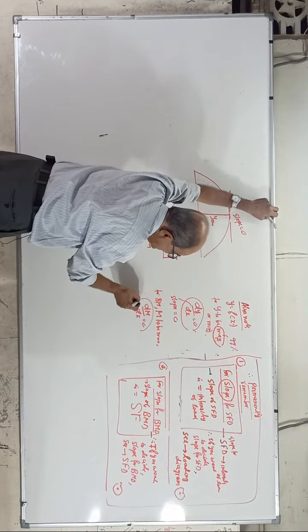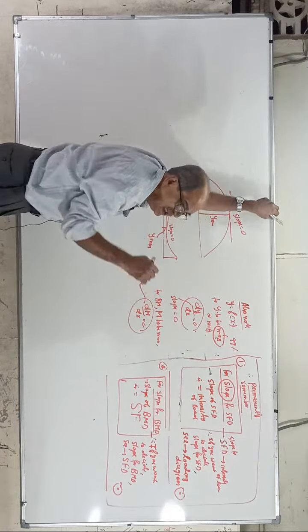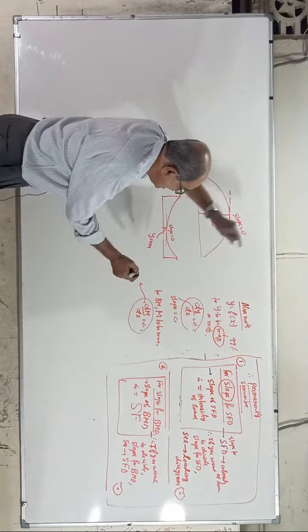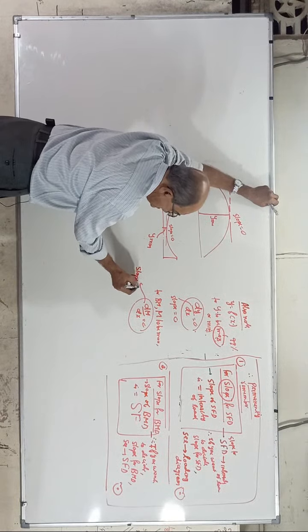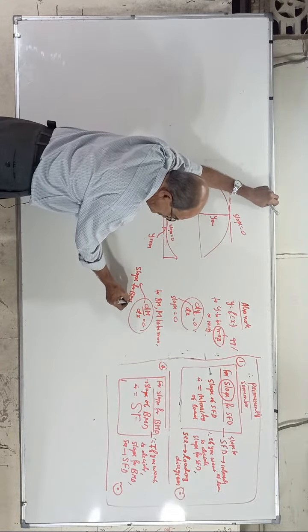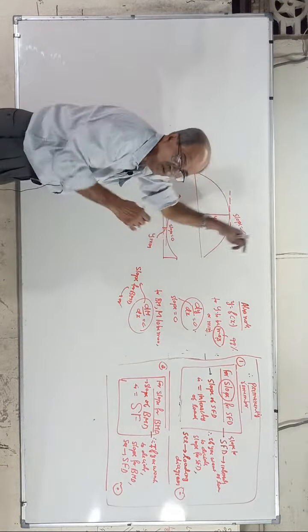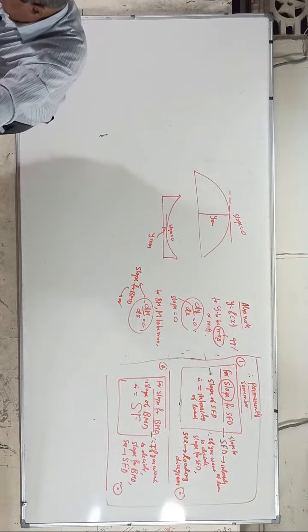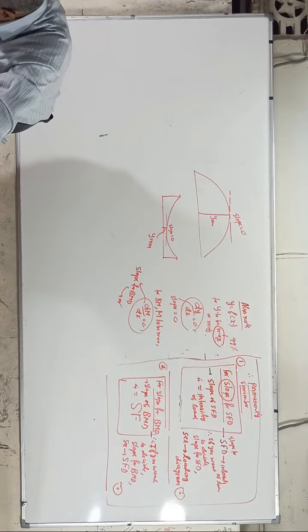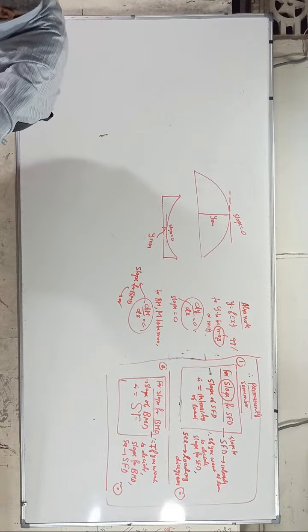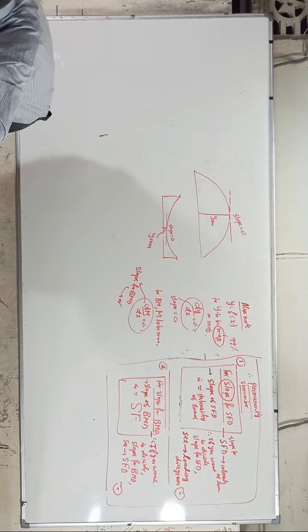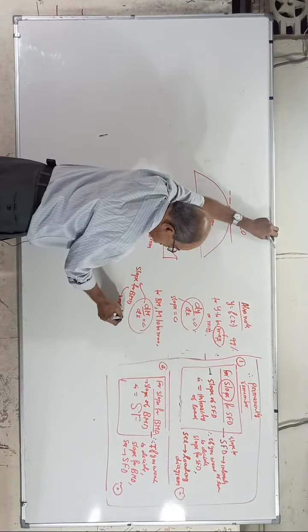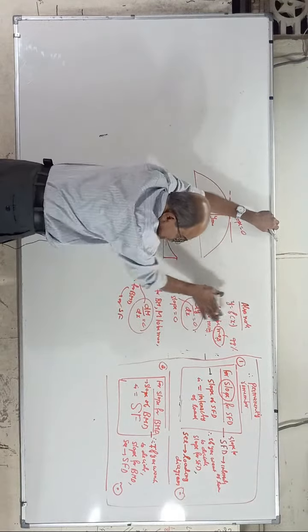But you know that dM by dx is what? Tell me. You know that dM by dx is the slope for BMD. This is the slope for BMD. Either you can say slope of BMD is 0, or you know it is the shear force. You know dM by dx is the shear force. Therefore, I will remove all this now.